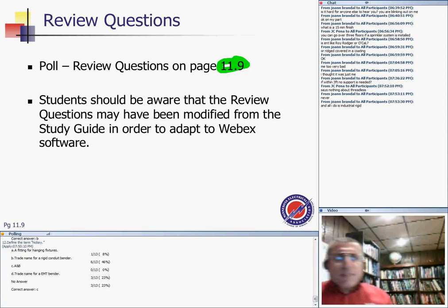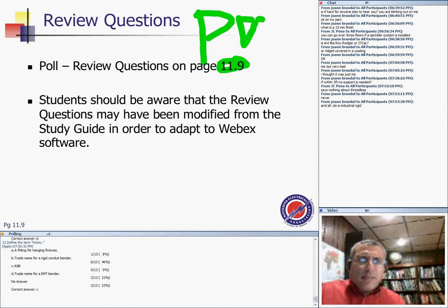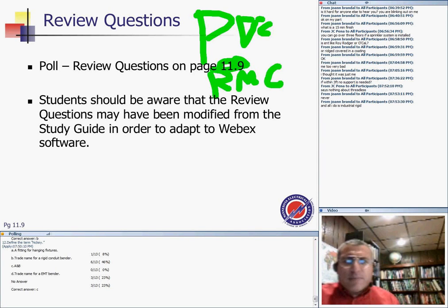Okay, I'm going to mention, guys, PVC coated rigid metal conduit. We installed some of this, guys. It gives you the advantage of rigid metal conduit, very robust, and also the advantage of PVC, in that you can install it in a highly corrosive environment.